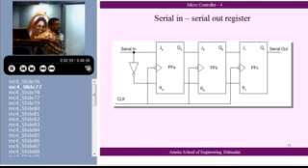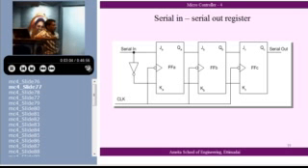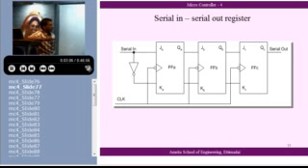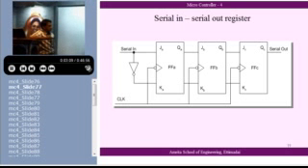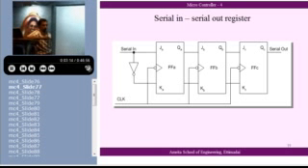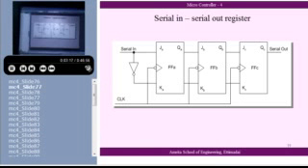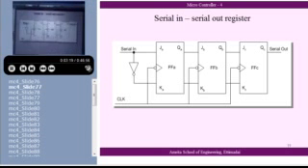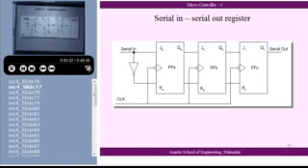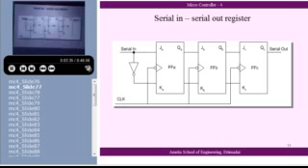I hope it is clear. The circuit, the way I have drawn it, is clear. Then, at the first flip-flop, I have given an external input. I have given this to JA, I have inverted this and given to KA, just like the D flip-flop. The outputs form the input to the next flip-flop: the A flip-flop output forms the input to B, and the B flip-flop output forms the input to C. The clock signal is the same for every one of them. Okay?